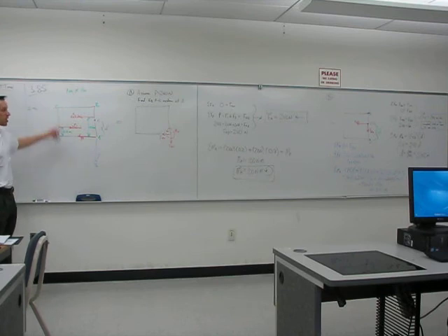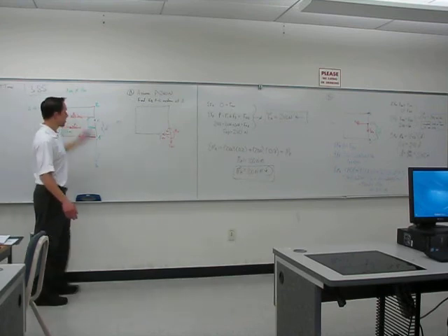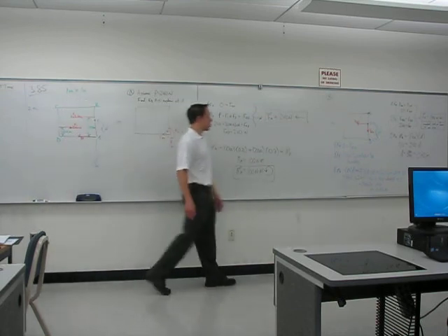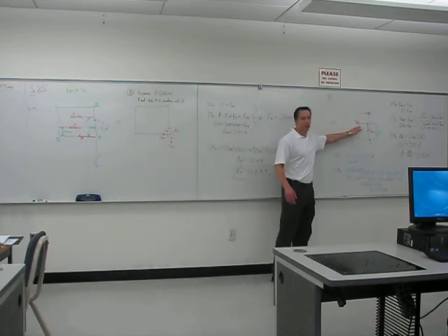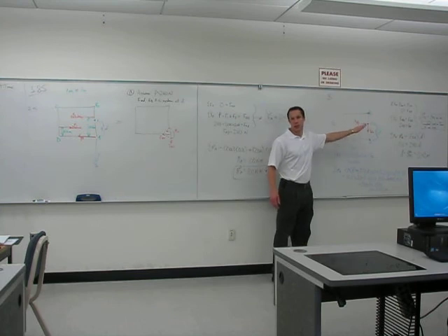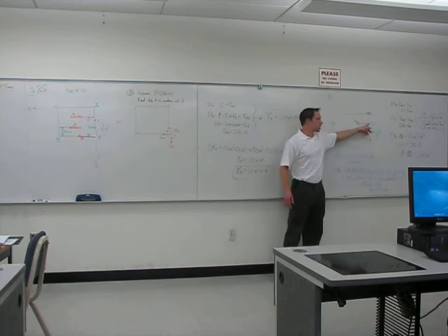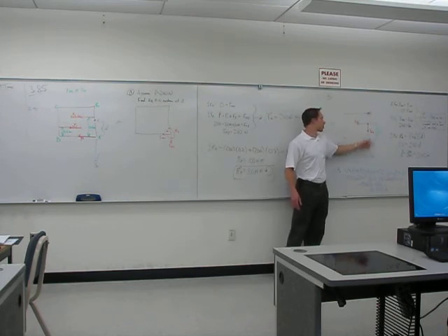You could take point C and find the sum of the moments around the point C. The sum of the moments around point C in this picture will be the same as the sum of the moments around point C in this picture, which will be the same as the sum of the moments around point C in this picture. Okay? So you can choose any point. It doesn't even have to be on the edge AB. Okay? Now they told us, in this second part of the question, to find a point on this edge where the force should be applied. So I knew that it was going to be somewhere on this edge, but I could still, for the equation, choose any point to take the moments about.